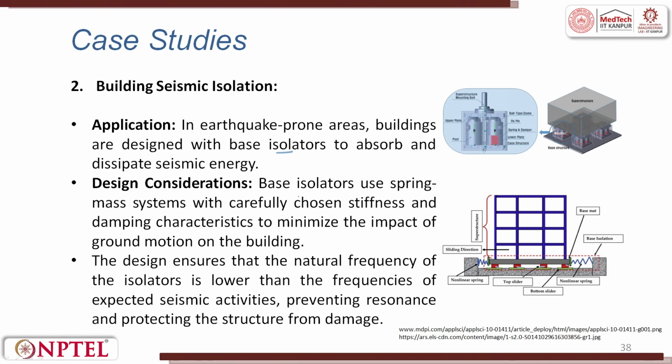Base isolators use a spring damper system in which the stiffness and damping characteristics are carefully chosen to minimize the impact of ground motion on the building. The design ensures the natural frequency of the oscillator is lower than the frequency of the expected seismic activity, preventing resonance and protecting the structure from getting damaged.